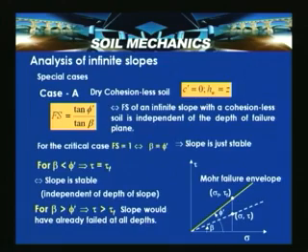So, this is a classical example for angle of repose. Suppose you wanted to form a dry sand heap, then you will not be able to make a slope steeper than its angle of repose. So, this is nothing but factor of safety is equal to tan phi dash by tan beta. A classical example which can be cited here is the formation of sand dunes. Of course, it varies from the windward direction and leeward direction, but the one governed here is tan phi dash by tan beta, where phi dash is the angle of internal friction of the material and beta is the inclination of the slope surface.